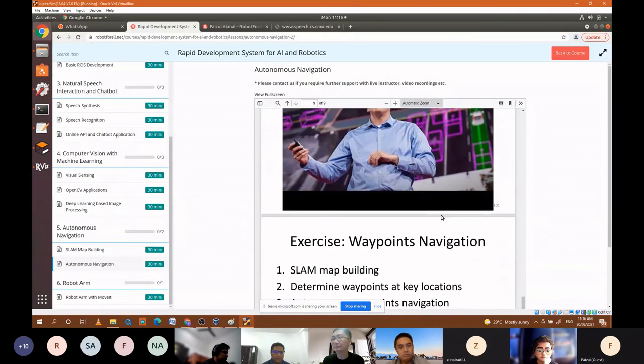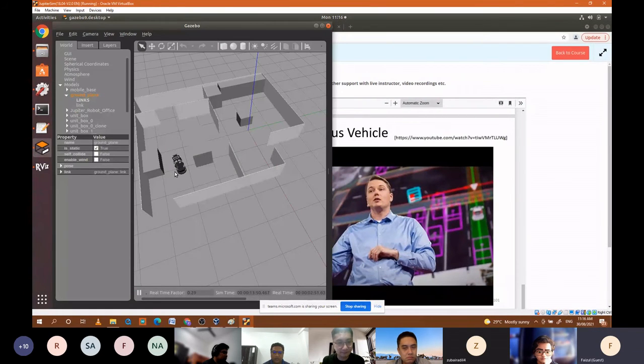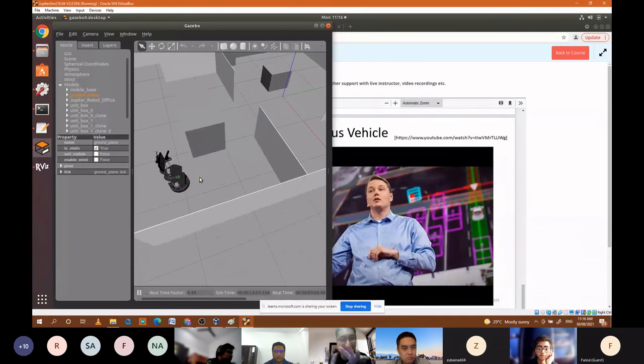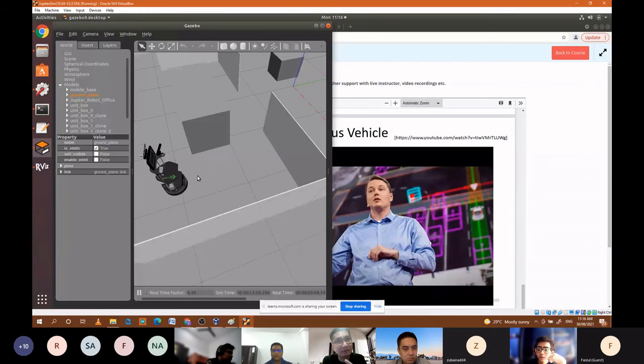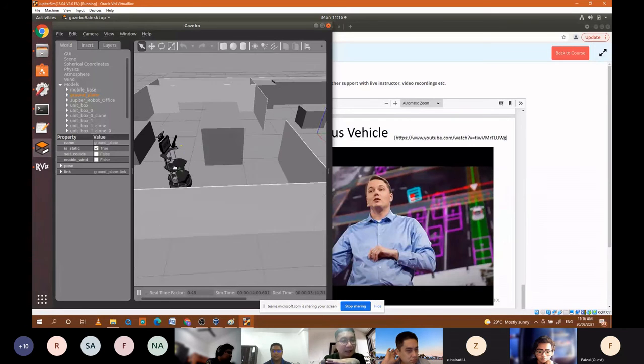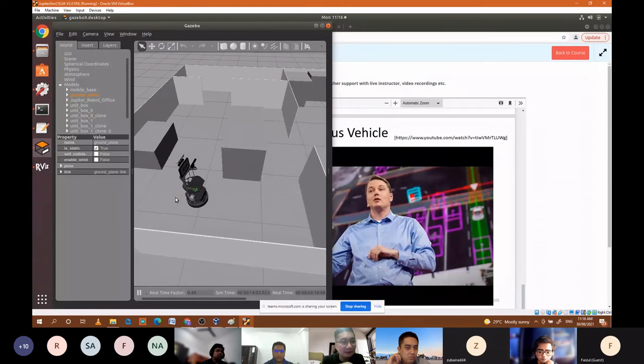In the Jupyter robot, there are two cameras, on the top and the bottom. What is the function of the camera on the bottom? Okay, this is by experience, I'm not sure whether it's accurate or not. Usually when building the map, I will use the RPLiDAR. But when I do navigation, I will use the bottom camera. The bottom camera apparently works better than the RPLiDAR in AMCL.